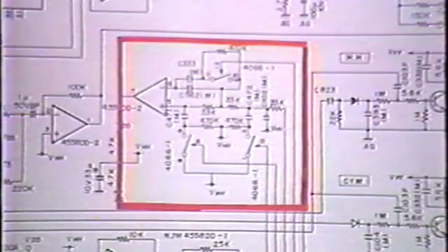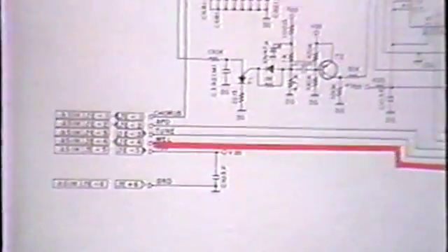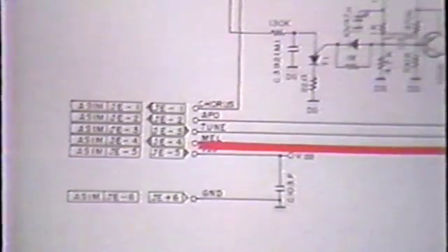The cutoff frequency can be varied by turning on and off S1, S2, and S3. These switches are controlled by the I01, I02, and I03 signals from the melody LSI. The melody signals output by the filter go to the JE4 terminal. This view of the terminal indicates that it is connected to the AS1M PC board through the 4 pins of the flat cable. The arrow indicates input or output.